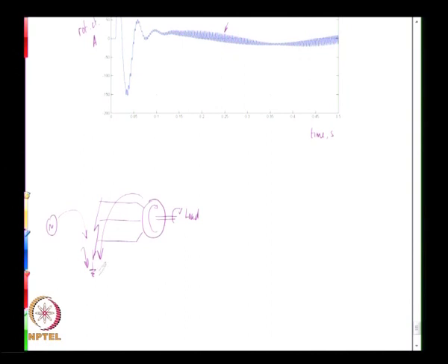It may be worthwhile to study what kind of fault performance this kind of system gives. If you want to study that, you need these kind of dynamic equations to see what is going to happen. But that is not all. If you have a system like this, because of the fault, at this point you might have a circuit breaker in the line. As soon as fault current is detected, the breaker may open, and if there is no breaker on the machine side, fault current will still be supplied by the machine.